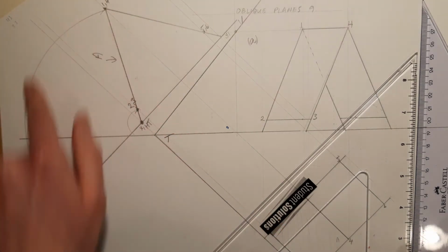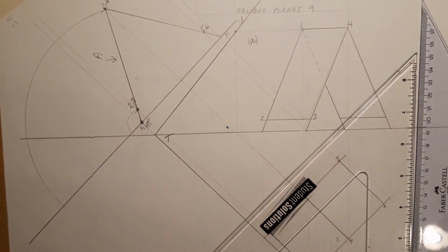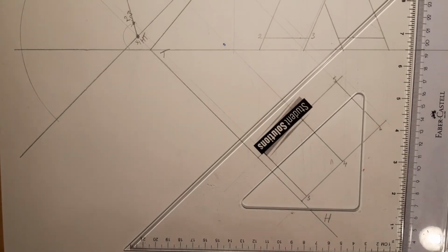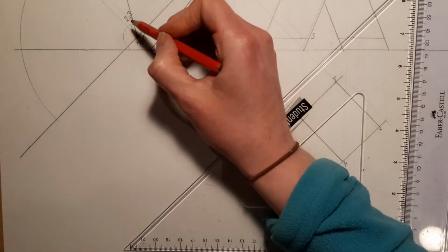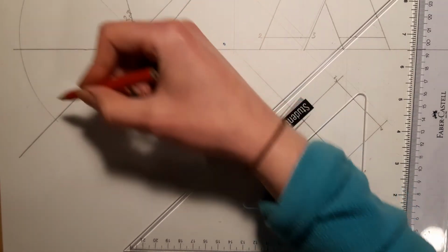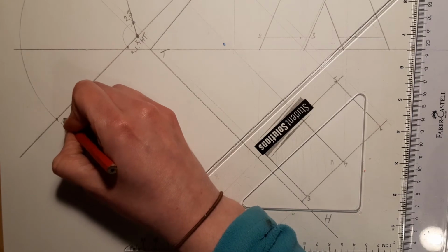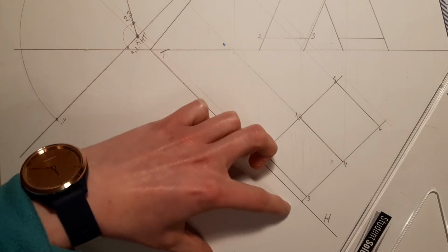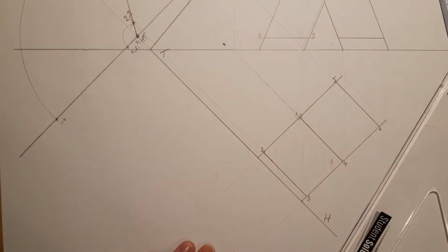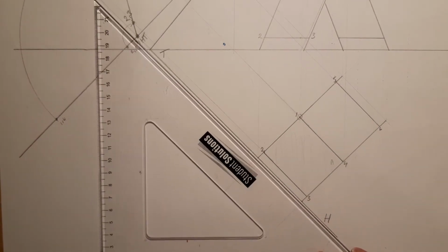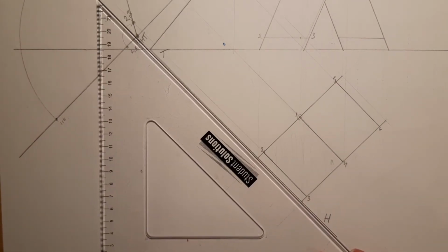Okay, so I've rotated both of those around. I've found them on the XY line. And I'm just going to ignore this for a minute by pushing this up. Okay, so you can see that I've turned 2 and 3 around. I'm going to label that 2 and 3. I've turned 1 and 4 around and it's now here. And now I'm going to bring back 1 and 4 and 2 and 3 back here. And I'm going to get the true shape down here in line with the plan. Okay, and you have done this a good few times at this stage. So it should start making sense, I hope.